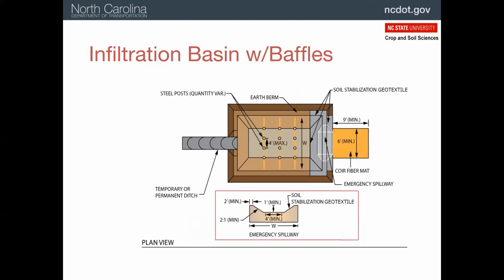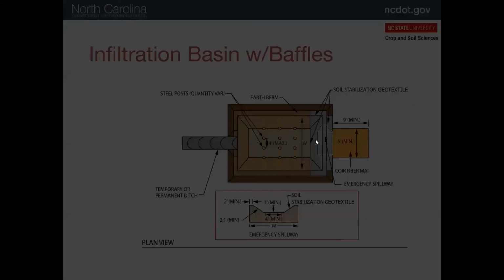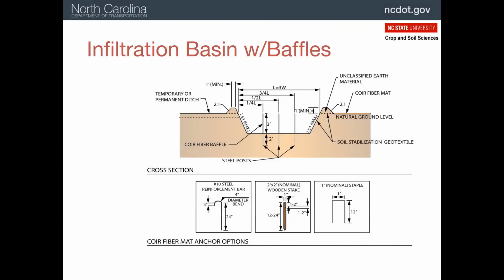Bird's eye view and cutaway of an infiltration basin. So it's just a skimmer basin without any kind of a skimmer, essentially. And there's another cutaway. We've got our 5-foot stakes, 3 feet above and 2 feet in the ground, evenly spaced.